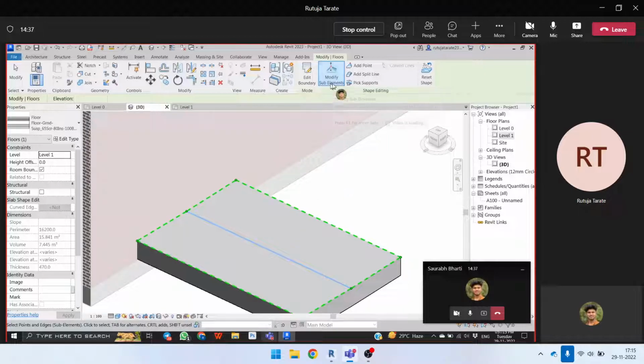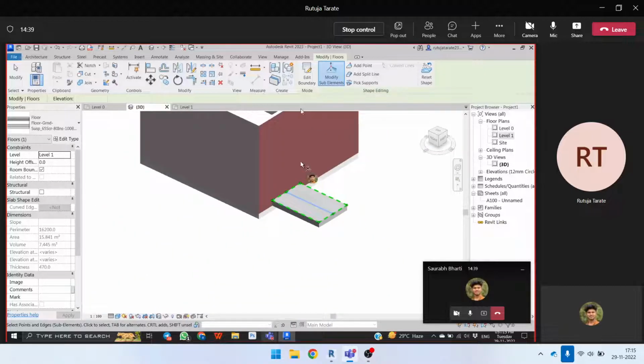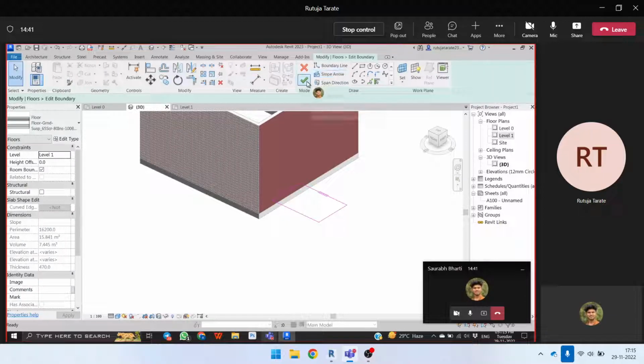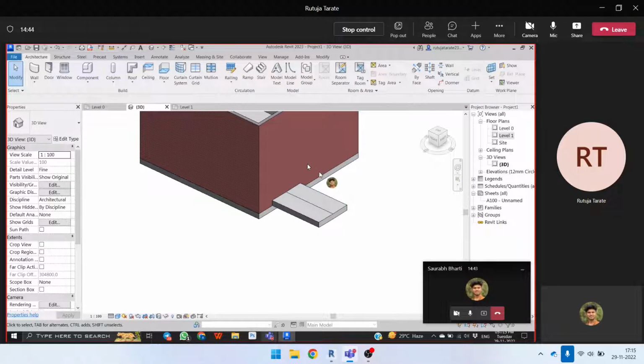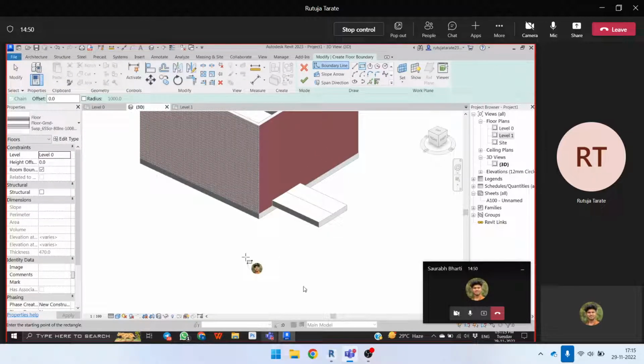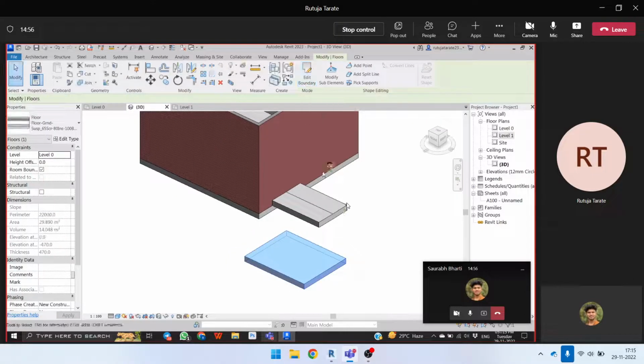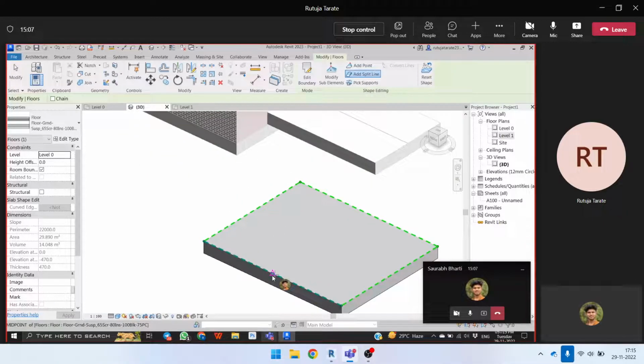Look, here you can just select the floor when you make it. Okay, let's just finish it. Let's make it once again. Here you have the floor. Okay, and here I'm just making it like a triangle, I mean rectangle. I'm trying to finish it. It's finished. After that, I will select the same floor. So I'm outside, I'm just selecting this floor, and then here's an option to add split line. Okay, so now I will split it from the middle from this point.